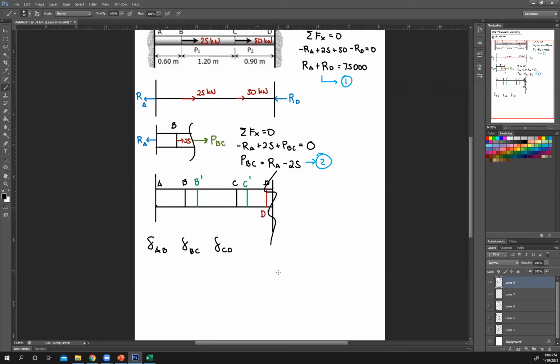Since you have constraints on both sides, the total length will remain the same. What can you say about their elongation and compression if it's restricted? Think about it. Two elongate, one compresses. What is the equation? What can you say about the magnitude of their deformations?